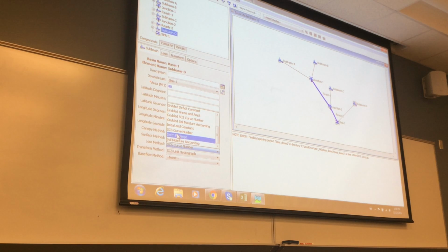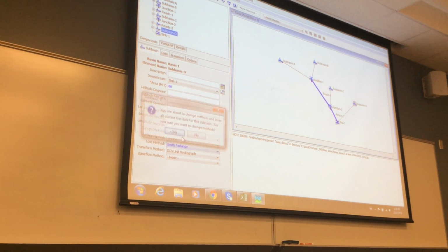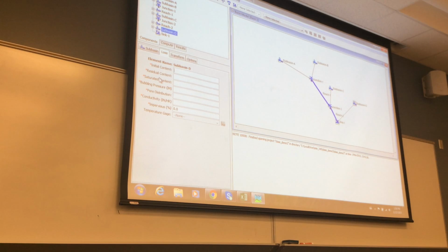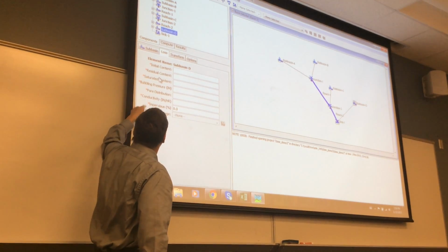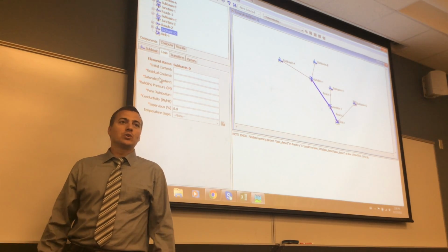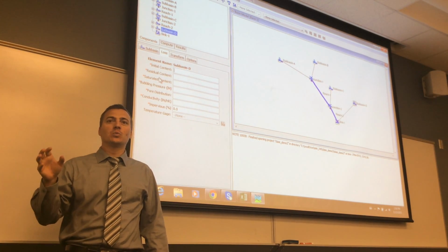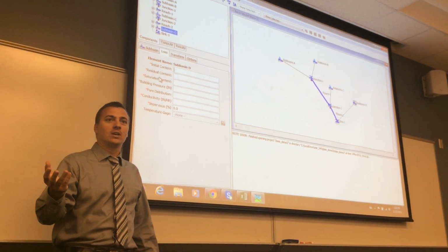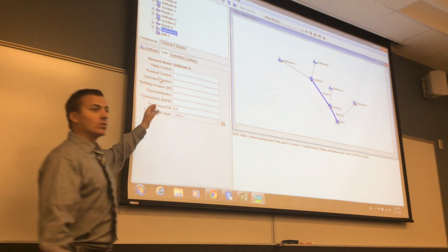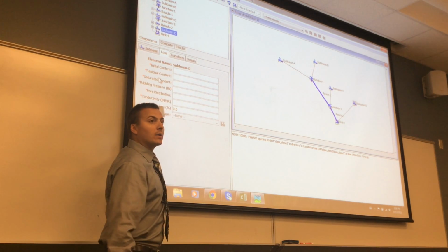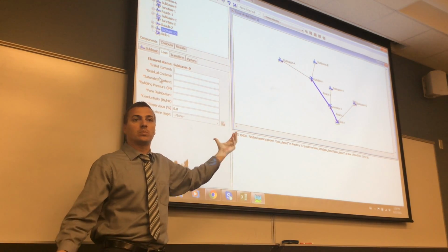If you want to use the Smith Parlange method instead of the curve number method, I chose that and go to losses. It asks me for all this, all the way to bubbling pressure. I have no idea what that is. So your choices have consequences. If you want to use a given method, you better understand what it is doing and have information for it. I've never used this method, so I don't know. But if you want to go with it, you need to figure out all of that, otherwise it won't run. Why? Because there's an equation underneath that needs those parameters.